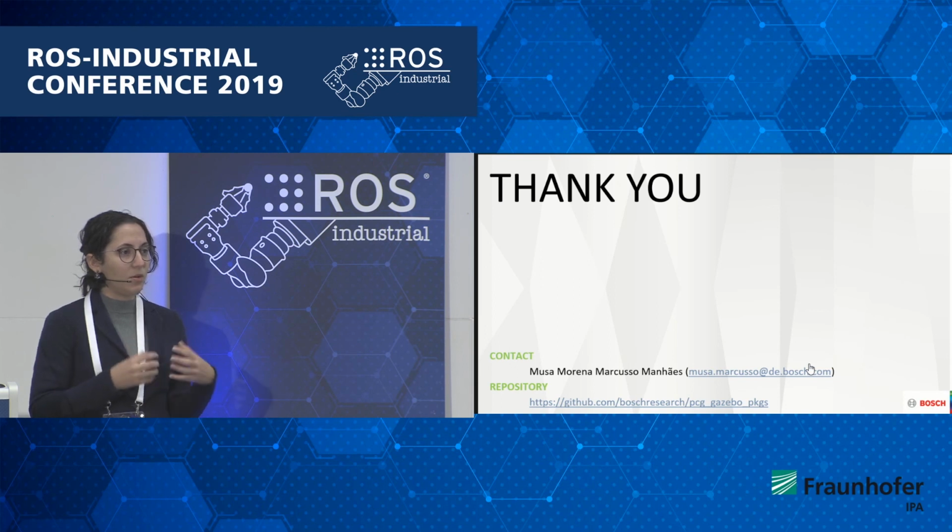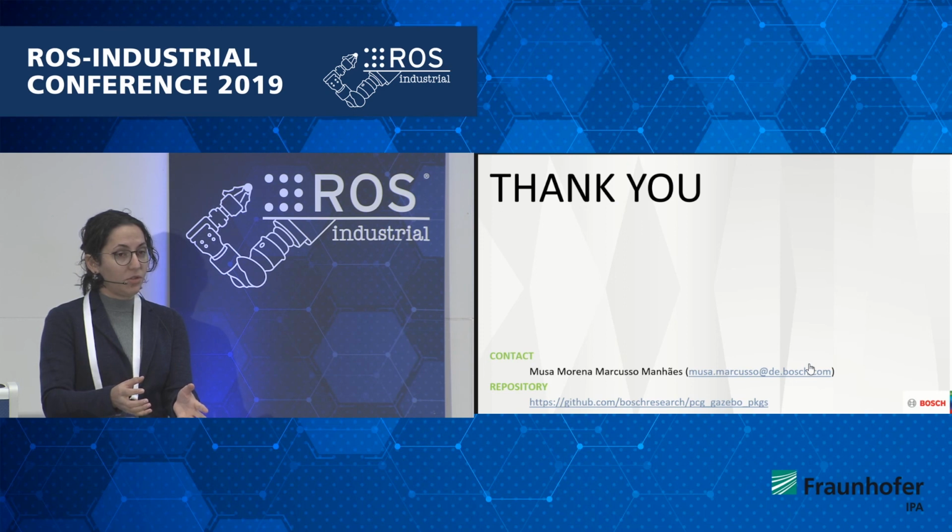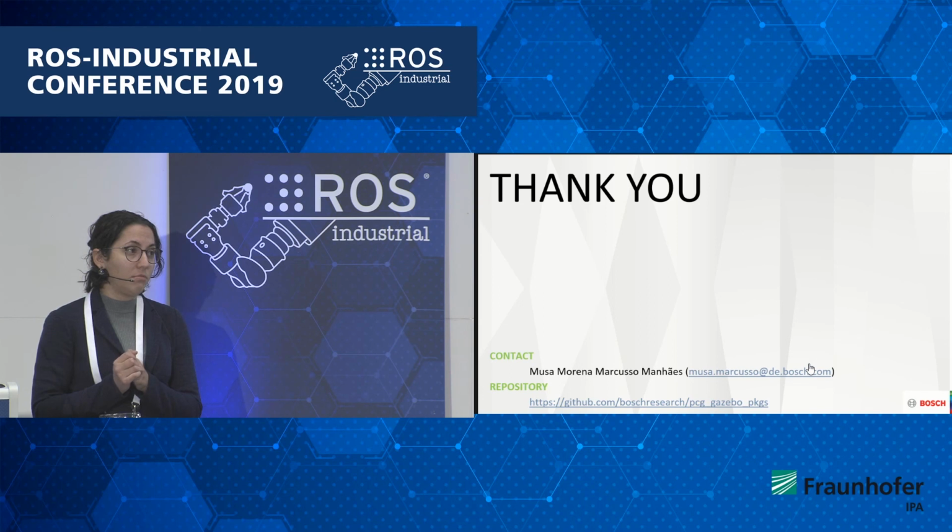So you can pass a whole dictionary with the parameters to configure the robot description and generate the template out of it. And I think Xacro is faster, that's for sure. It's faster to generate the robot description on the fly, but the amount of functionality is not that great. I think with Jinja you have more freedom to build very complex robot descriptions if you want to.